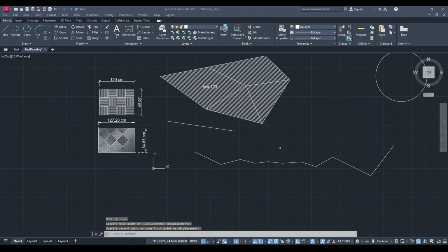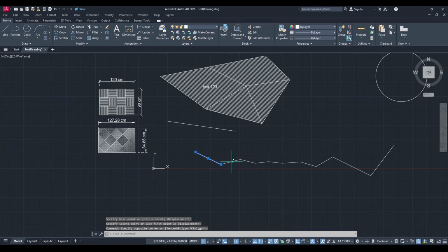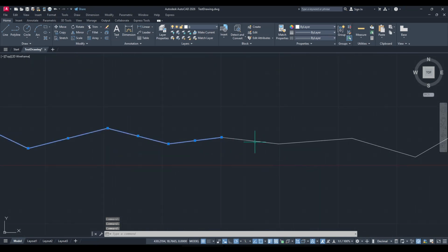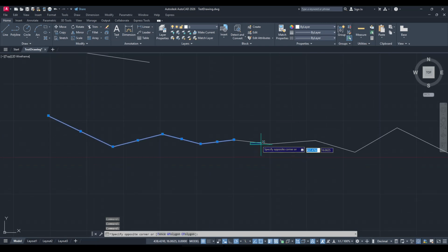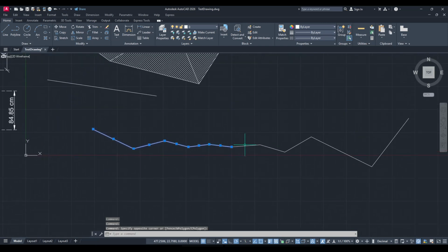In today's video, I'm going to teach you how to convert line to polyline in AutoCAD. Turning a group of separate line segments into a single, clean polyline is a small step that unlocks a lot of power. A polyline lets you offset the whole path at once, apply a uniform width, fillet or chamfer continuously, and measure total length without adding up each piece.